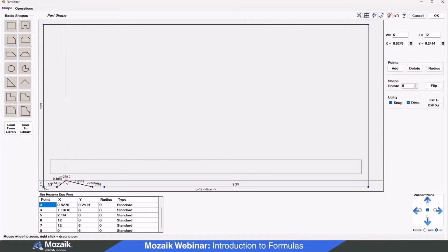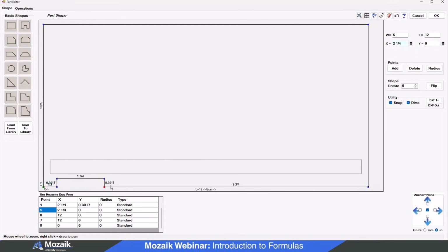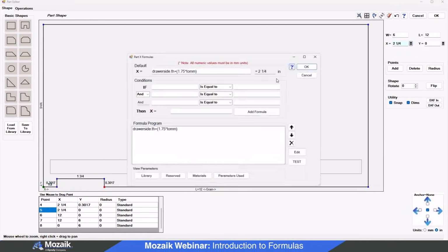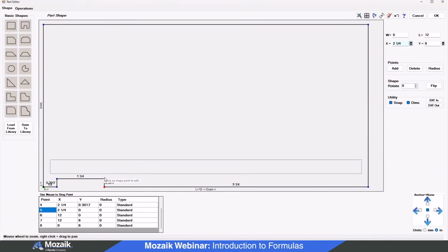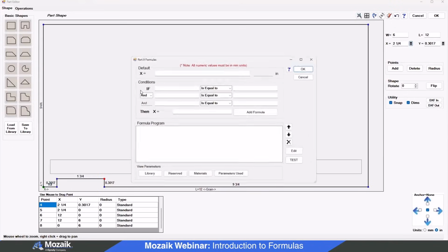Now the shape editor here is pretty slick. It's going to snap to 90 degrees. So you can see it's kind of snapping to the points there. But I need to make these also parametric, because if I was to stretch this right now, these nodes would not stay in the proper position. So we'll do this one first. I'm just going to copy the X axis. So I'm just Control C, and we're going to pop this into this one here.